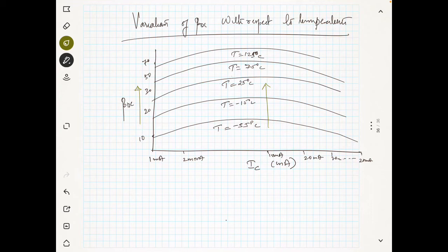If you have a transistor circuit which is designed for Abha, and you take this to Riyadh during a hot climate or a hot season, what will happen? There will be a small variation in the beta. According to the variation in beta, you can see a small change in the collector current also. As the collector current changes, VCE changes. So there are different techniques to solve this issue by using a clever circuit design.